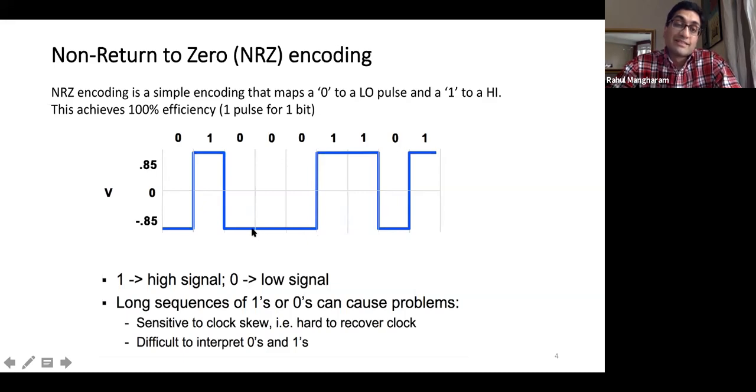But when I receive it, I may be 30, 40 hertz or 100 hertz or 200 hertz slower or faster than you. And maybe I just detect right over here that that's the end of a bit, and then I start the next one over here. So that just means that your clock and my clock are offset by some rate, right?